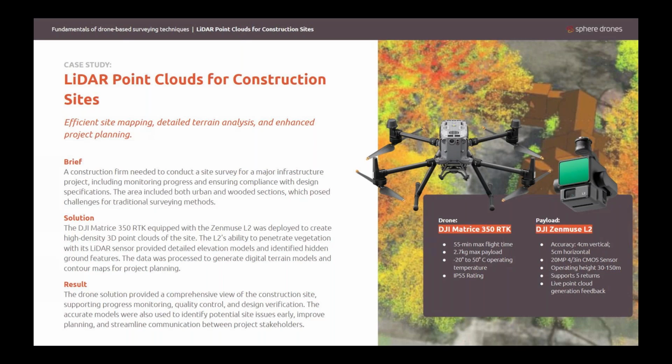Yeah, the L2 is a really nice piece of kit. Having a live view of the LiDAR point cloud as it's capturing is really neat, and having the ability to capture high-resolution imagery with that built-in camera is really handy as well. If higher accuracy or precision is required, then one could step up to something like the Surveyor Ultra by YellowScan.